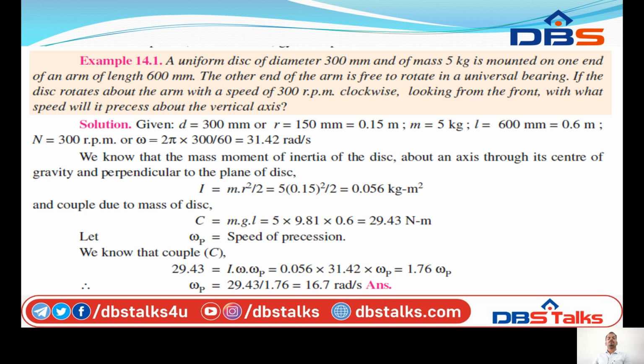So we can directly get the normal speed, that is n, also from here. We know omega is nothing but 2 pi n by 60. So we have to find whether that speed is the angular speed or the normal speed. Okay, both are good for results. From omega p only we can get it directly, np.